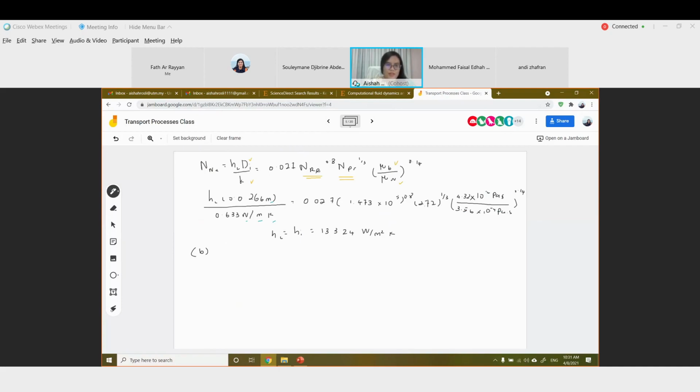If you remember, the heat transfer coefficient U_i is equal to this formula. It is also, if you remember, the typical energy balance equation, where the heat transfer rate is equal to the driving force divided by the resistance.